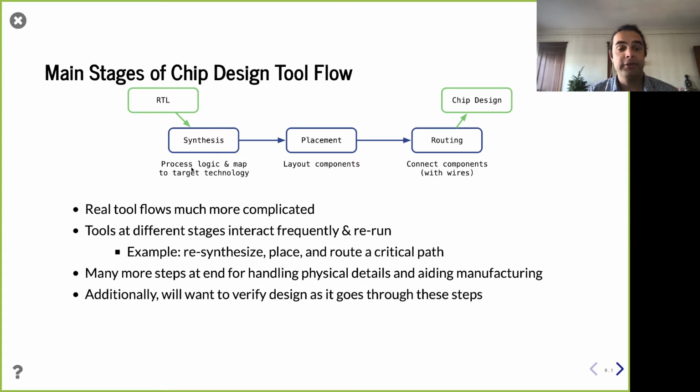which takes your Verilog and turns it into things that map to your target technology. For example, if you write a certain statement in Verilog, and here is, let's say, an AND, that needs to be mapped into an AND gate in your implementation technology. Working with an ASIC technology, you may have what are called standard cells, a standard library of building blocks, things like AND gates, registers, etc. And so let's go ahead and map those.